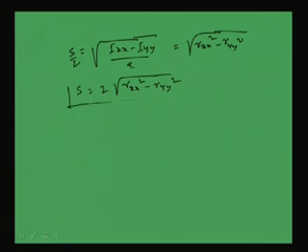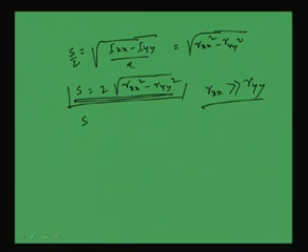So the spacing between 2 I sections should be more or less equal to this for economic design. If it is exactly the same as this expression, then we have the most economic design. Now if Rxx is much greater than Ryy, then further simplification can be made by dropping the term Ryy. So S will become 2 into Rxx.